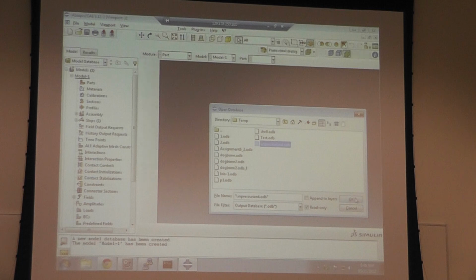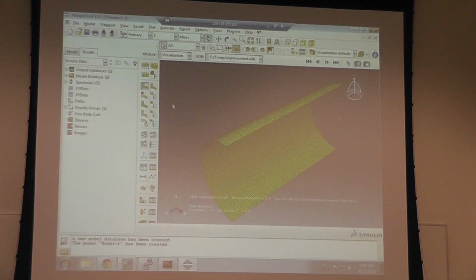So the unpressurized pipe will do the following. I'm utilizing a quarter of the pipe because it's symmetric. Now I'm applying bending moment here. As it buckles, I can use a quarter of the pipe to model the whole thing. It's symmetric around these lines, and the load is applied at this point as a bending moment applied on the whole end.